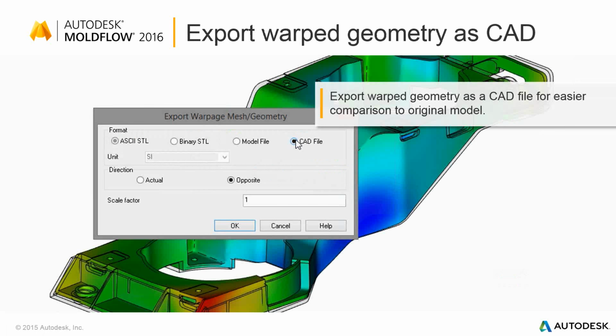This is another one that I think is going to be super useful. So if you brought in your CAD model as a CAD solid model and you run a warpage analysis on it, we can now use the deformed mesh from, let's say, your dual domain or your 3D model, the warp mesh, to morph the original CAD model into basically complying with the deformed shape.